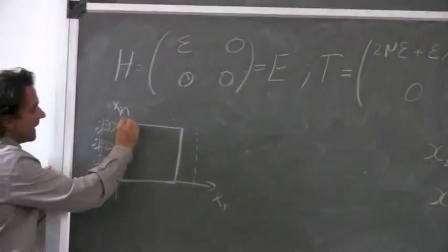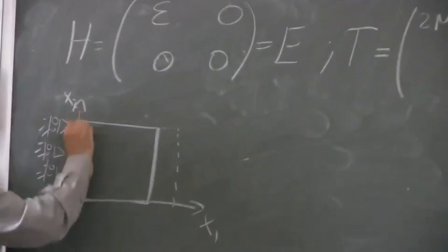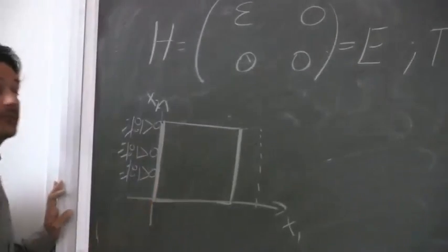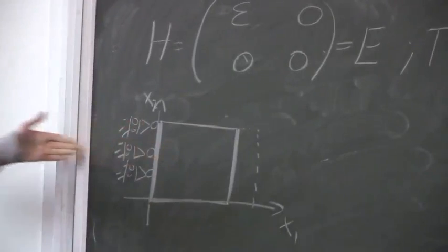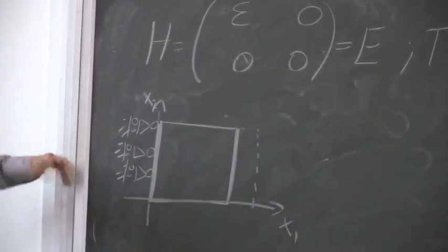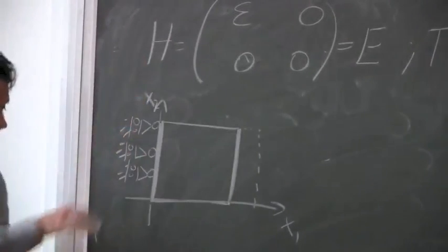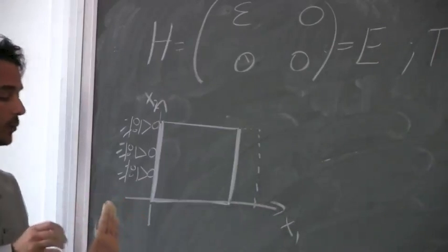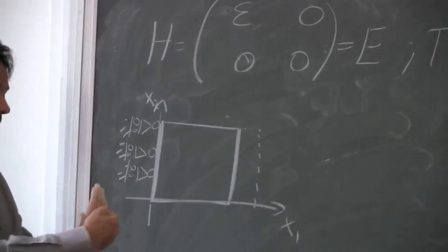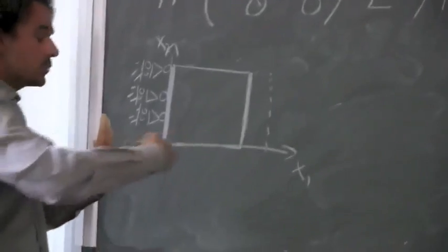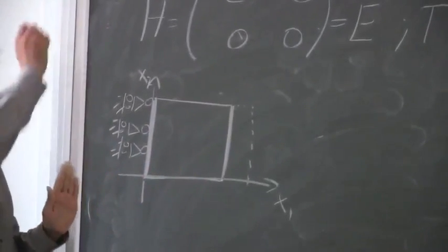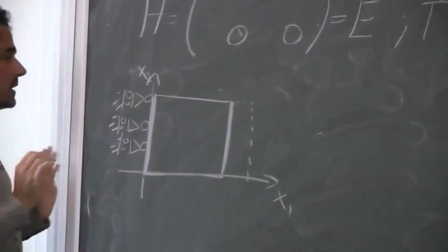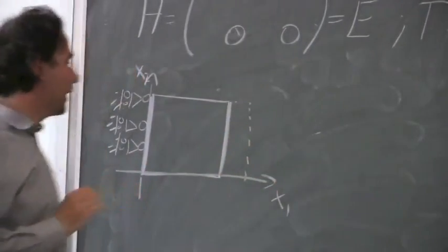So we prescribe that this surface is fixed, but it is fixed only in this direction. This is a square, and we impose only that the displacement in the x1 direction is 0, but the displacement in the other direction is free. We see how.